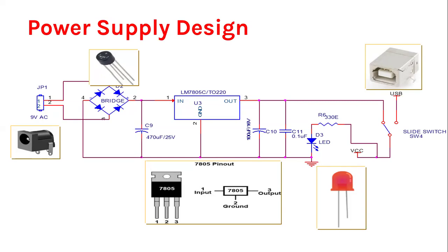To convert the phases, we use a rectifier circuit. Once you use the rectifier circuit, the output has only one phase: the positive phase remains and the negative is converted to positive. But it has some pulses. What we need is a constant magnitude, a fixed 5 volts, drawn as a straight line. But after the rectifier circuit, it looks like clouds, with some ripples in the signal.